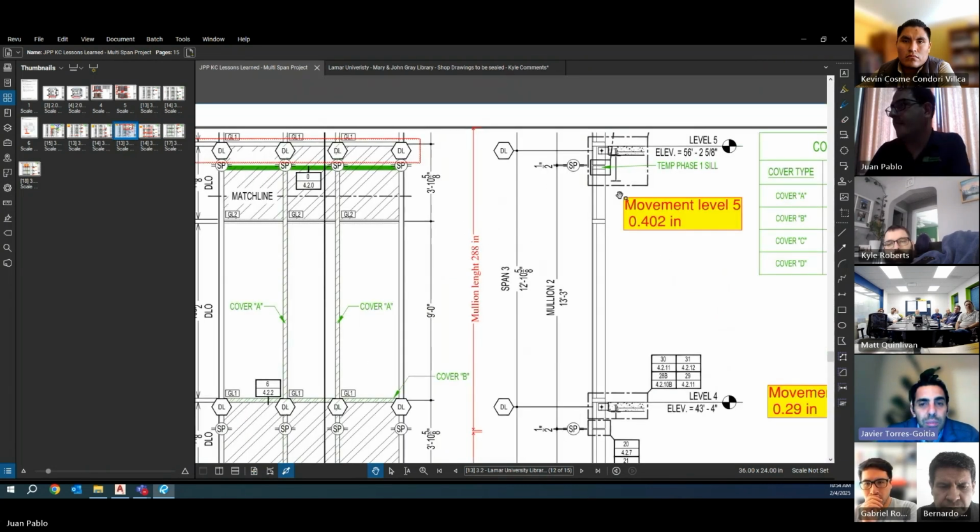If we were to put a splice in those spandrel areas, we would still run into the glazing pocket clearance and bite limitation that Kevin presented before. But that's a good point. We always want to try to use spandrel areas, which are typically right underneath the slab, to hide those splices. But in this case, because of the live load movement, it wasn't an option.